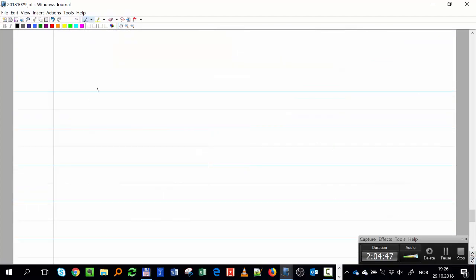Okay, we said Bg will be at pressure and temperature, with its density. How do I express the density in standard conditions? Remember, P standard conditions times V standard conditions equals R times T standard conditions. But density at standard conditions is 1 over V standard conditions. So you can express it as density at standard conditions equals P standard conditions over R T standard conditions.